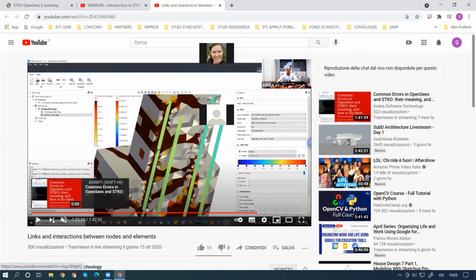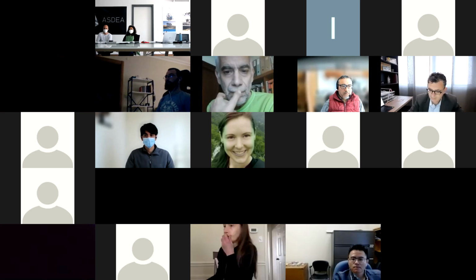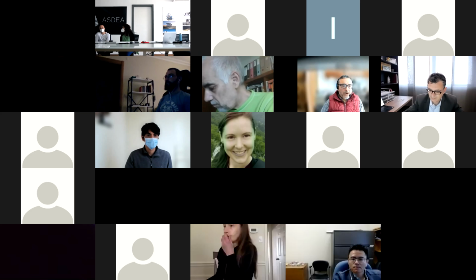So we're not going to model rebars separately inside the solid elements, but we're going to do fiber sections with rebars. This other one is a detailed model, a solid model of rebars explicitly modeled inside the solid domain of the concrete. There is also the bar slip interaction, so it's something more advanced. We are not going to cover micro modeling in this course series.